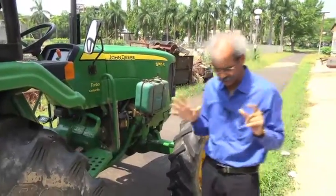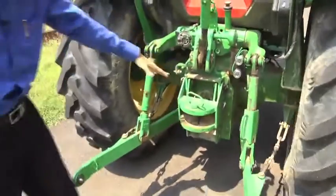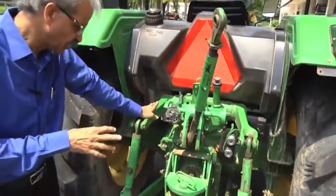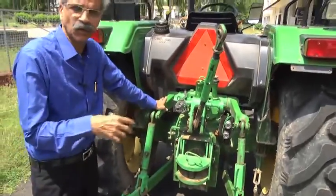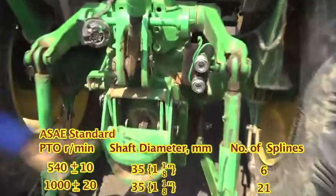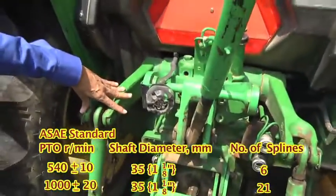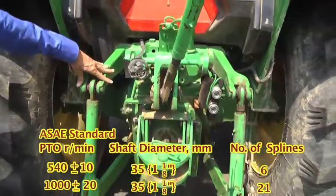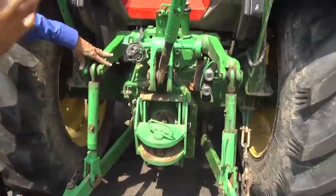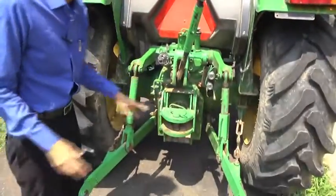Now, when we are talking of taking the power out of these tractors, we have three main power outlets. One is the PTO, which is in fact of two types. Generally, a PTO will have 6 splines or 21 splines. These are for 540 plus minus 10 RPM, and then another 21 splines will have about 1000 plus minus 20 RPM.